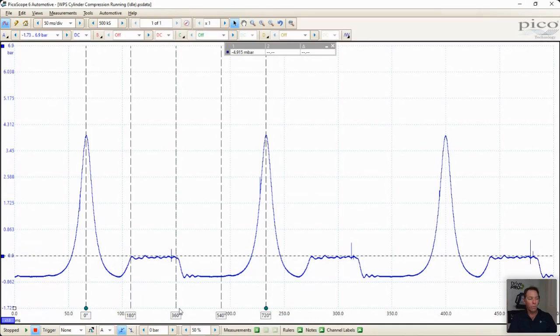Now we also know somewhere before top dead center my intake valve opens on all engines. And we can actually see where the intake valve opens here with this little bit of noise on the pressure transducer. So we know shortly after the intake valve opens, the exhaust valve closes. Now, because our piston's traveling back down, our intake valve is drawing air into the cylinder. The cylinder pressure is now lower than atmospheric, and we can see the cylinder pressure drop down here, atmospheric pressure, cylinder pressure. We can now see back around here at bottom dead center, that's taken a full charge.